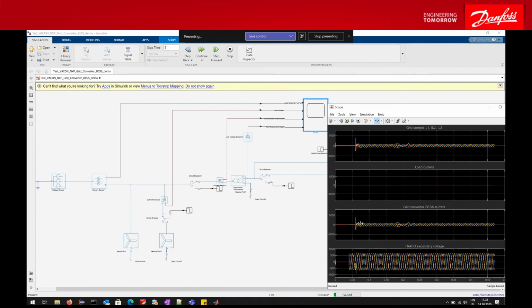And this one here, the third picture, this is the current on the primary side of the transformer, but it's the current coming from the inverter. So we can see here that this is the instant where the inverter starts, or the breaker is closed, so that the filter is... this is the filter inrush current, and this is now the current taken by the filter capacitors of the LCL filter. And actually this is the instant where the inverter goes online and starts here.